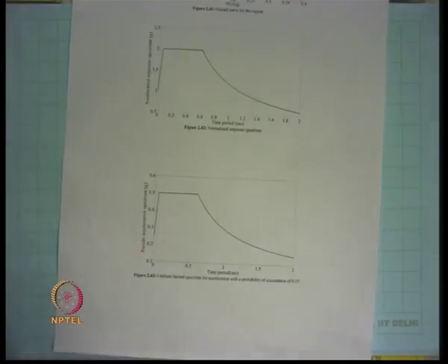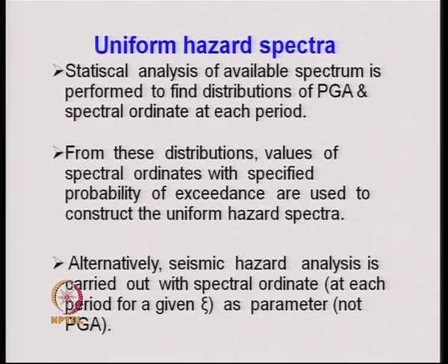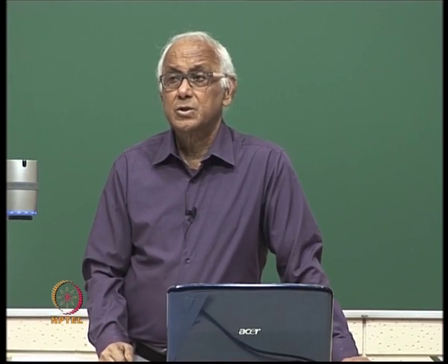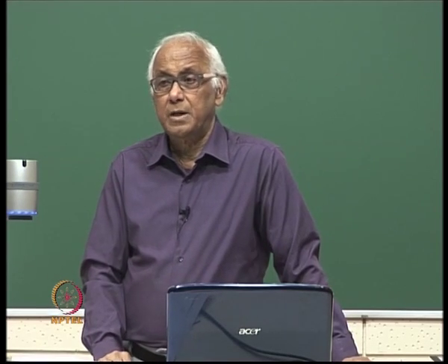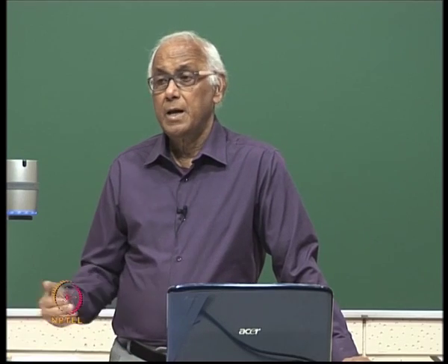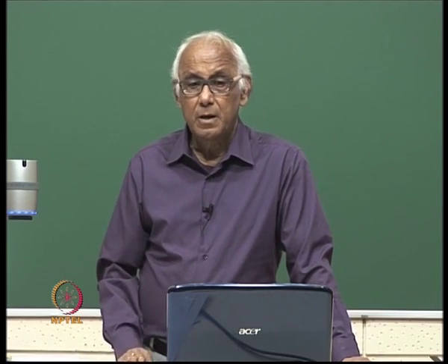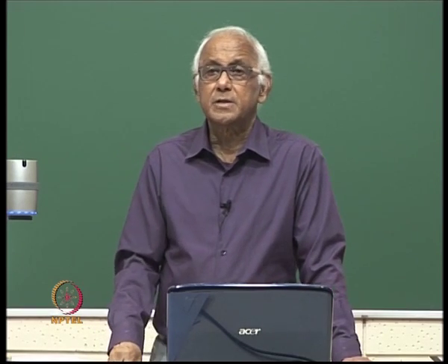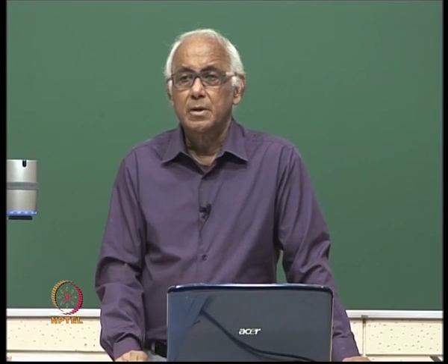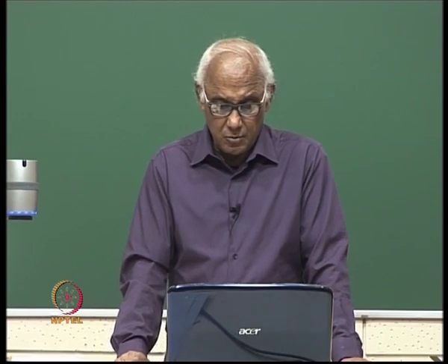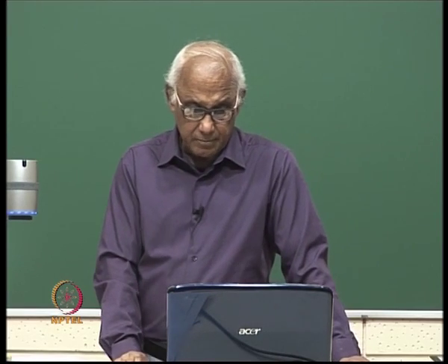And so, the procedure that we adopt depends upon the given quantity that we have. If the given quantity is only the time histories, then these time histories are to be scaled for the peak ground acceleration or magnitude of earthquake and epicentral distance through Fourier series analysis. If it is given in terms of the power spectral density function, then the procedure that I have mentioned can be used in order to get the site specific spectrum.